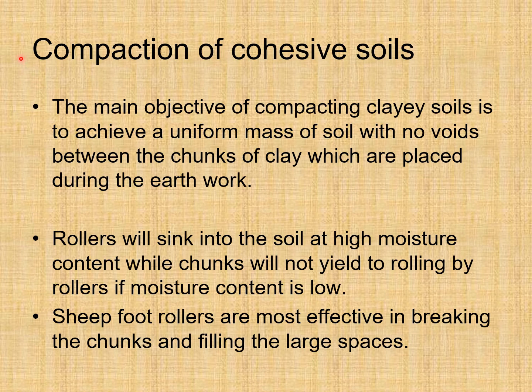Compaction of cohesive soils. The main objective of compacting clay soils is to achieve a uniform mass of soil with no voids between the chunks of clay which are placed during the earthwork. Rollers will sink into the soil at high moisture content, while chunks will not yield to rolling by rollers if moisture content is low.